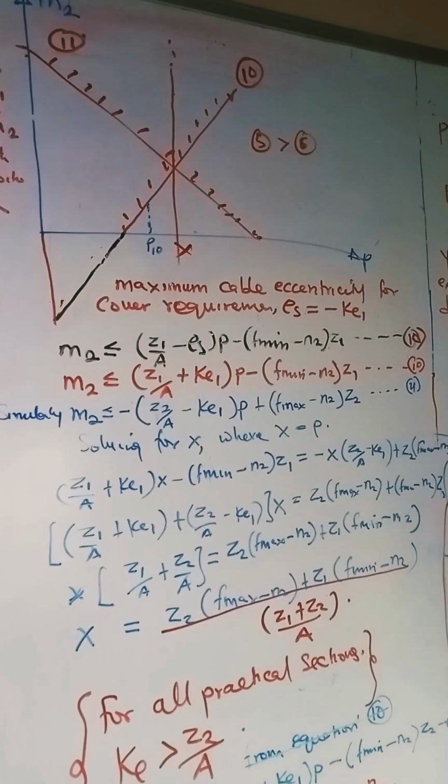Also ensure that where it becomes necessary to increase the pre-stress to get your cover requirement, instead you just increase your section so that you have adequate cover. Okay, so that is that for this first case. Remember, this case is for M1 and M2 both positive. So let's look at the value for our pre-stress, the value for cover in case 2, which is negative.